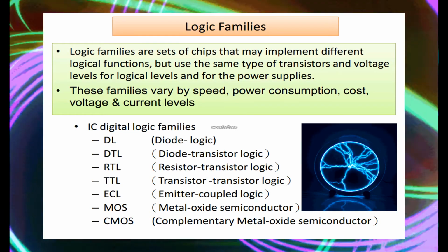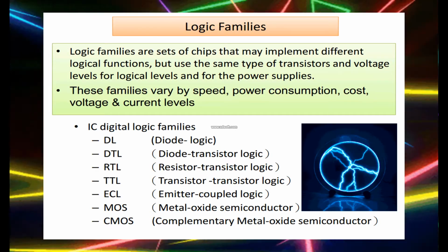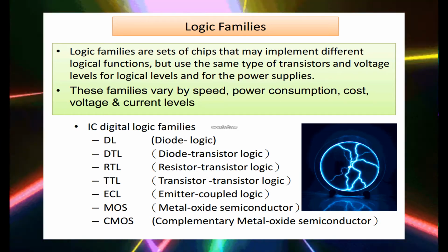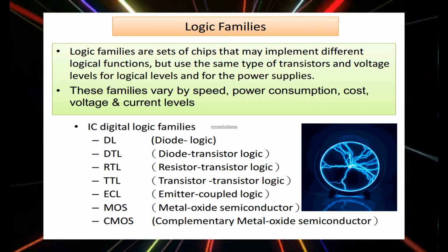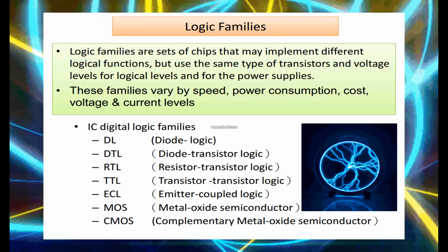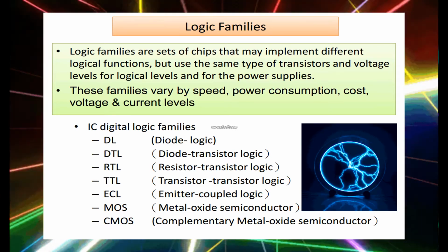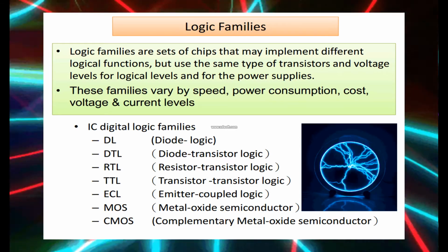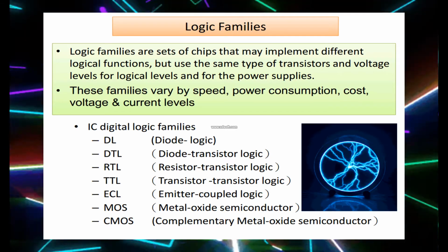This slide gives some information about logic families. Logic families are sets of chips that may implement different logical functions but use the same type of transistor and voltage levels for logical levels and for the power supplies. These families vary by speed, power consumption, cost, voltage and current levels.